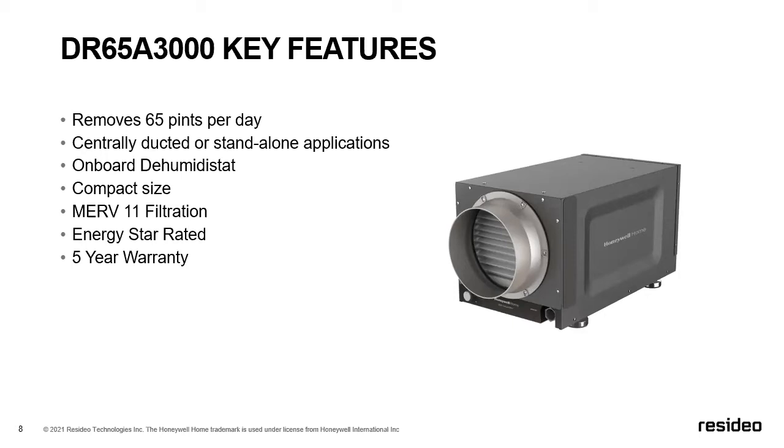Those application questions, you can reach out to your Resideo rep or distributor partners, and we can talk through that. But the DR65 can be centrally ducted or standalone. We do see the DR65 in a lot of standalone applications in the South, in crawl spaces. Maybe we've got a crawl space we're looking to dehumidify. We can stick that machine underneath, drain it, and it has an onboard dehumidistat, so it doesn't need to be externally controlled. It can have an external controller or not, but we do provide an onboard dehumidistat for those standalone applications where we just want to set it and forget it.